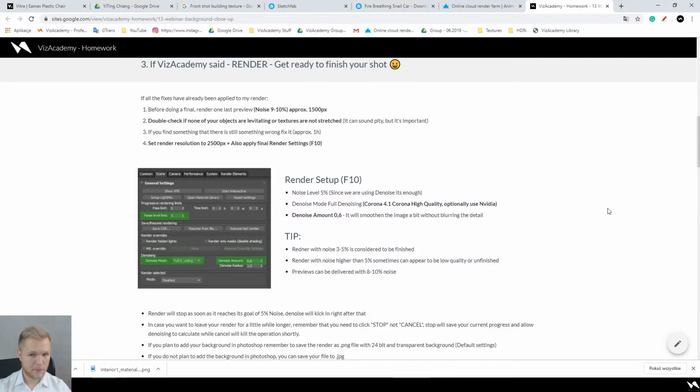And remember that with noise limit set to 4 or 5, you can start using NVIDIA Fast Denoise or NVIDIA AI or whatever the name you have right now in it. The NVIDIA is going to be okay as long as you have a newer NVIDIA graphics card. This is the only reason why a graphics card may play a role when buying your computer, but remember, it's not that important.